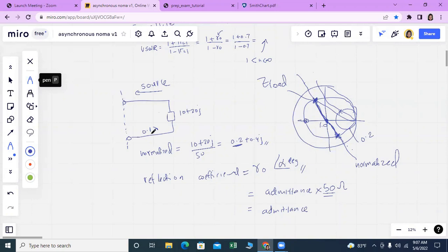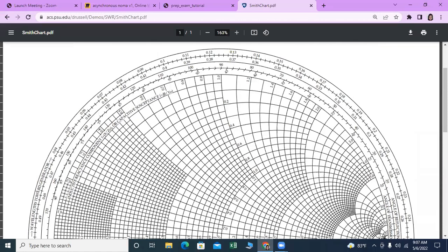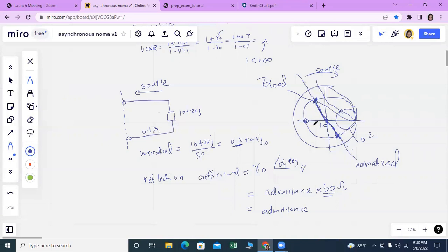So in the Smith chart, from the load point, you have to travel towards the source to find the input point. You have to travel a 0.1 lambda distance to find the input point. In the Smith chart, you can find a certain scale, which is given as wavelengths towards generator, in the outermost scale. So using that scale, you can measure a distance of 0.1 lambda, and then you can go to that point and mark it.